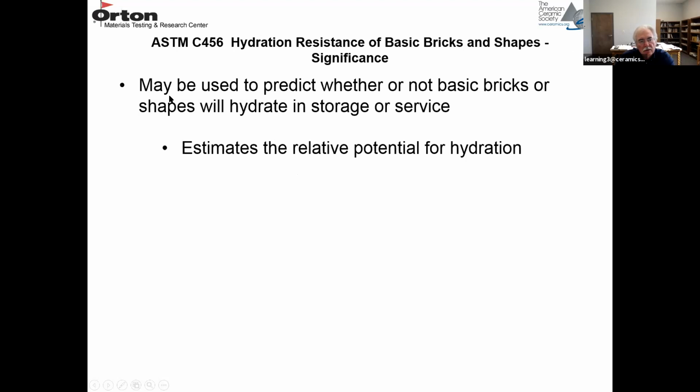The test can be used to predict whether or not basic bricks or other shapes will hydrate in storage or in service. And I mentioned that dolomite will hydrate rather quickly in storage unless it's protected. It still has a relatively short shelf life. You can also use this test to estimate the relative potential for hydration.